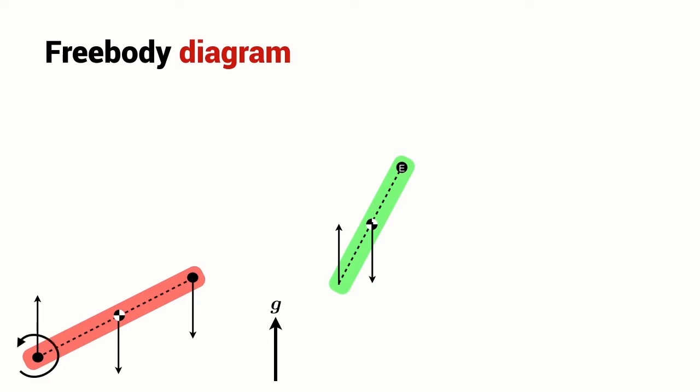Now there is a moment provided by the motor which is driving joint 1. It is providing a torque to stop the red link rotating. And similarly, there's a torque applied to the green link by the joint 2 motor to stop the green link from rotating. And then there is a reaction torque, equal and opposite torque from that motor, which is applied to the red link.